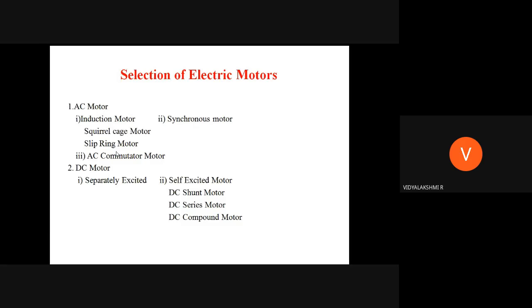Before that, you should know the starter concept. The starter is nothing but, as already said, in order to limit the starting current, I have connected the resistance with respect to the motor. The main function of the starter is to limit the starting current. What is there in the starter? It is all made up of resistance only. There, I have connected a number of resistances.